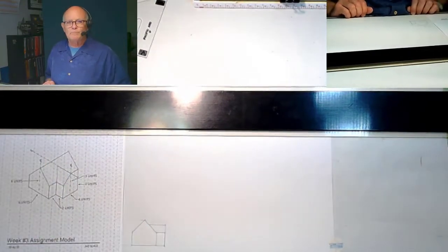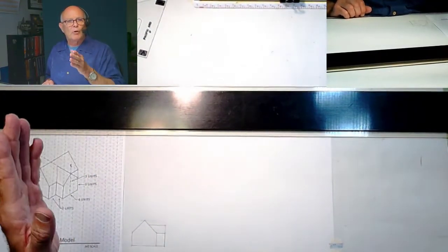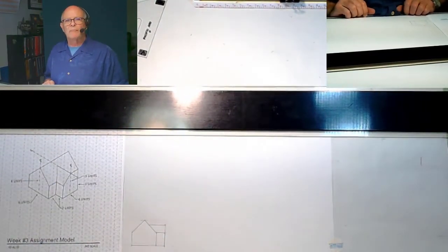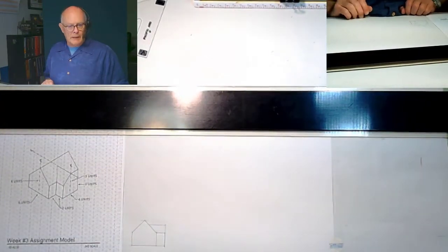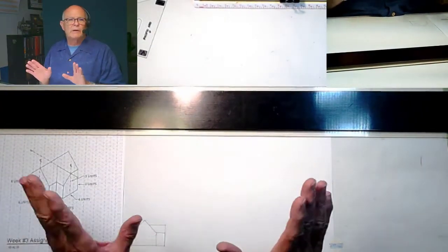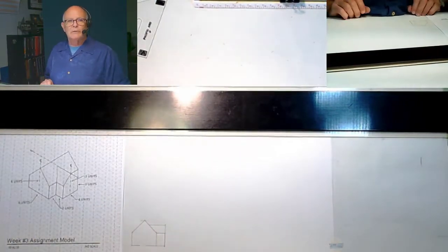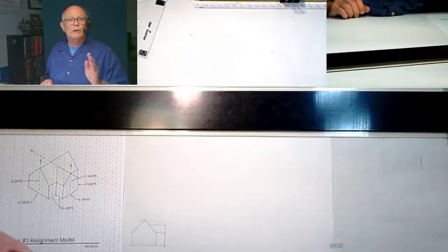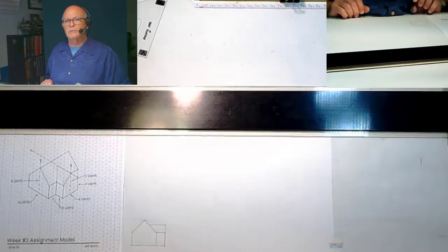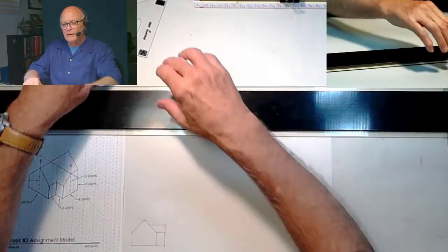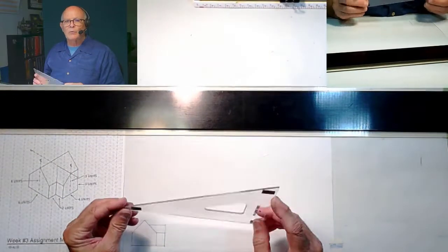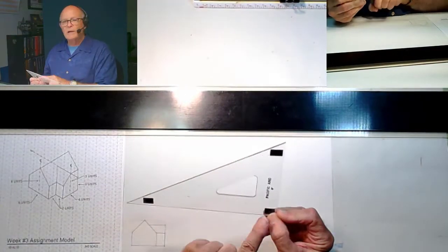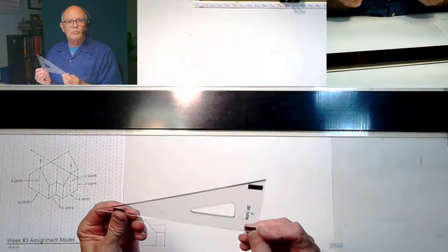So the first thing you need to know, and a rule for all three of these paralines, is that vertical lines will always remain vertical. Horizontal lines, which are represented here, will vary by drawing type. And so in this drawing type, the isometric, we're working with a 30-degree angle off horizontal. And so we're going to look at using a different triangle. We're not going to use the 45-degree triangle. We're going to use the 30, 60, 90 triangle. And this will give us what we need.